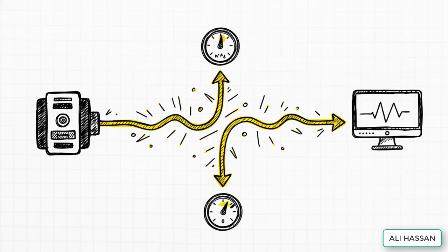And here's the really clever part. Using 4 milliamps for zero means that if the signal ever drops to zero, the operators know the wire's been cut or the sensor failed. It's a built-in safety check. This simple idea is what modern automation is built on.